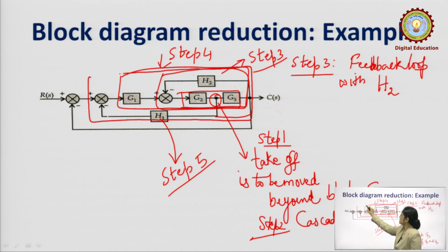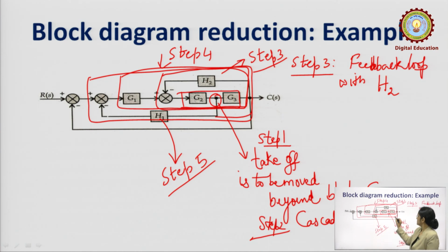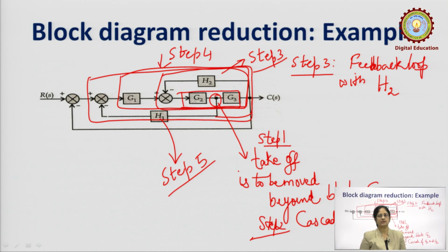After that the block is this much. We can see that the feedback path is moving. Here there is no block, that is, the output Y(s) is fed back directly to the input. In this case, the gain here is treated as 1, and since it is going to a minus sign, the gain here will be minus 1.